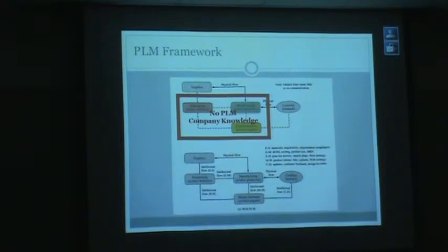The only thing they can't do is overwrite the models. So if they're in your PLM system looking at things and they tweak something and they go to say save, what's it going to allow them to do? Save a new version. They can't drop it on top of the Boeing release version. They can set up a new Korean version with a special extension to it that says we've tweaked it, we've modified it.